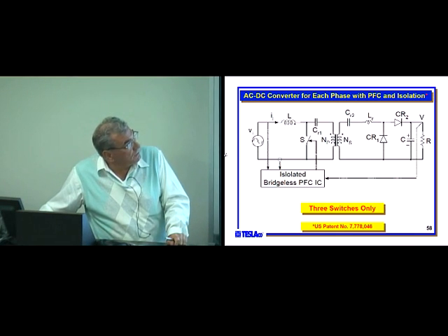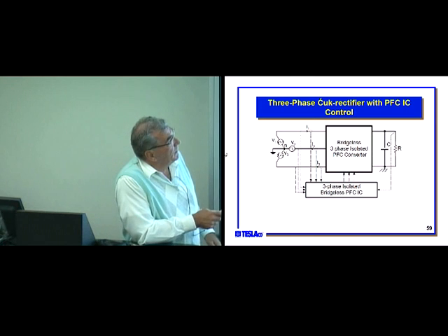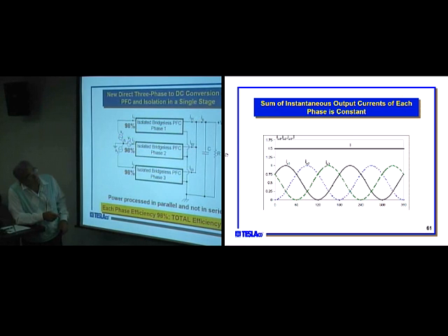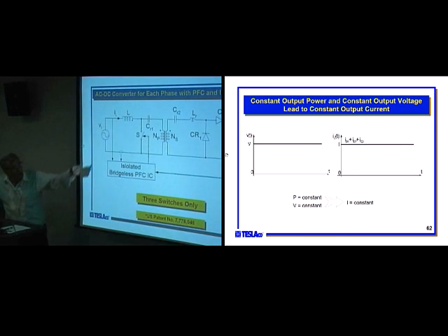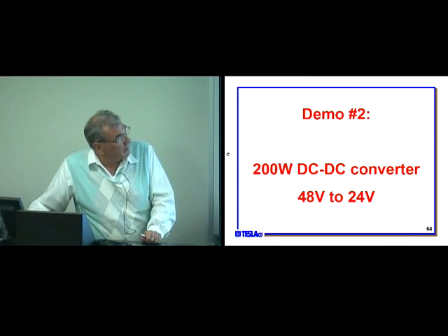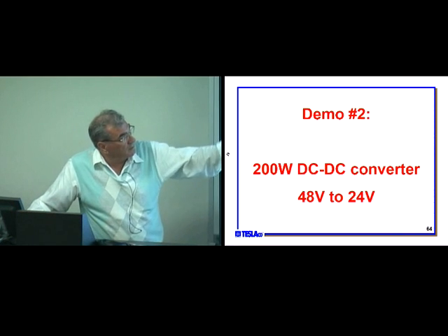We have three converters, each one operating from this, but 120-degree phase shifted, and all three combined together into basically the DC current. Therefore, each one supplies what's needed, just like a three-phase system, with no energy storage needed in the system. And each phase has this simple three-switch converter. And this is basically what it shows, DC current.